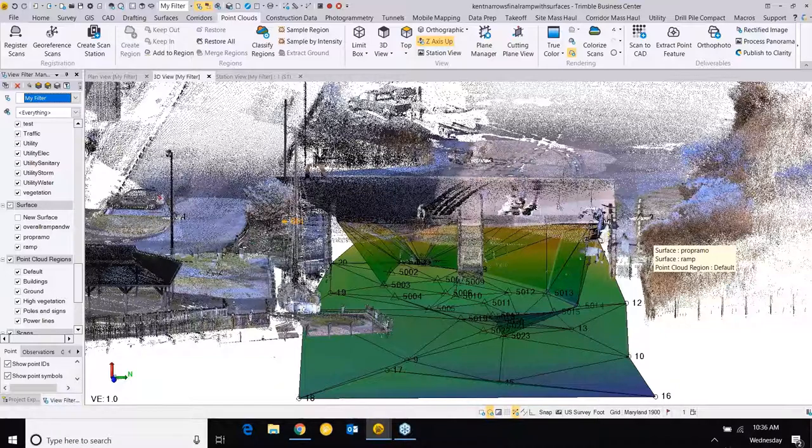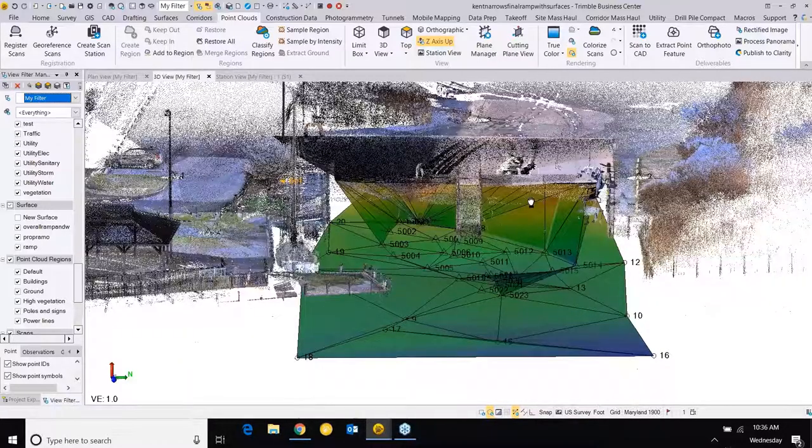Now, there's something you can do in here as well for driving and 3D drive. Usually you can have a surface selected, so I'm going to select the surface and say overall surface here. It's a cheap way, but it's something nice. You can go to Corridors and there's a 3D drive button.